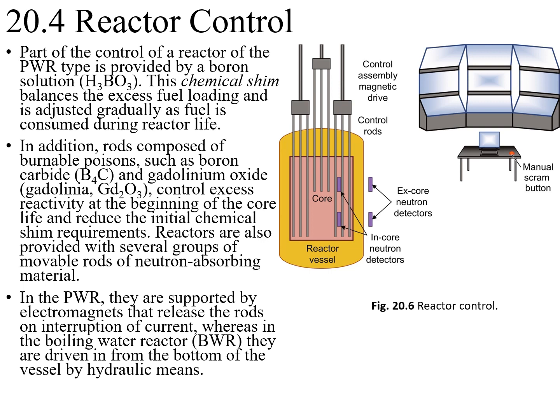In the real world, the reactor is controlled using different methods. The first one is by introducing the boron content into the coolant or into your moderator. Because boron is a neutron absorber, by introducing the boron into the coolant, you can absorb neutrons. If you have more boron, then you can reduce your reactivity more. This is called the chemical shim.